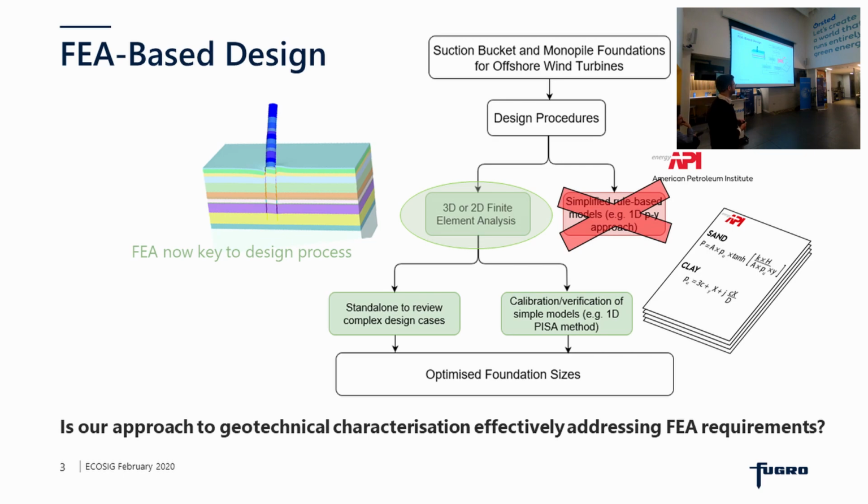And in fact, to such an extent that really, for monopile design and for suction bucket design, the simplified conventional offshore rule-based assessments contained in sort of ISO and API code are really not doing the job to adequately constrain that design case. And therefore, FEA really is a key to moving the design process forward for those foundation types.